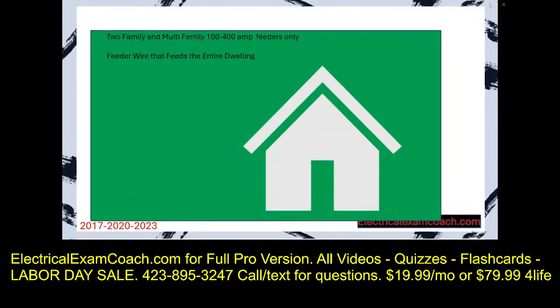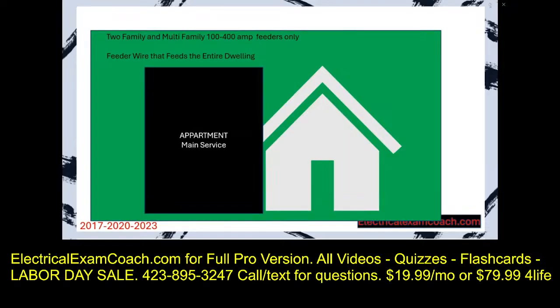Let's dive into two-family and multifamily. This is 1 through 400 amps, and this applies to the feeders only. The feeder must feed the entire dwelling. Let's imagine that you have an apartment here on the right-hand side, and it's attached to the larger apartment structure. That's where the main service is.